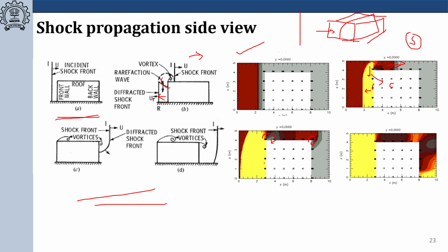So previously we have discussed that the reflected pressure is used to compute the loads, but that is only on the front face of the structure. So here we have an incident pressure traveling forward. Which pressure history will you be using here? Sorry, you will be using Cd times q, that is the drag pressure onto the surface. That will be the pressure history you will be using on the sides of the surface.